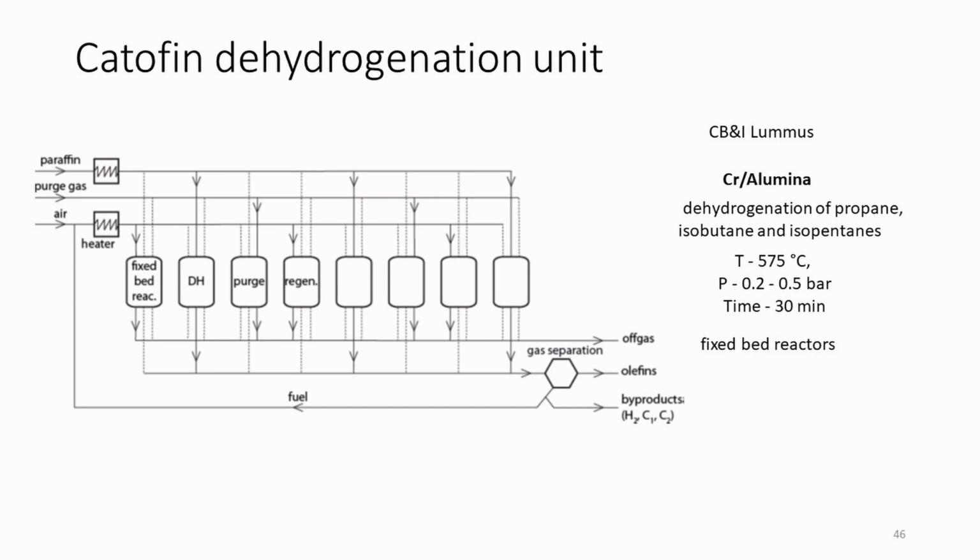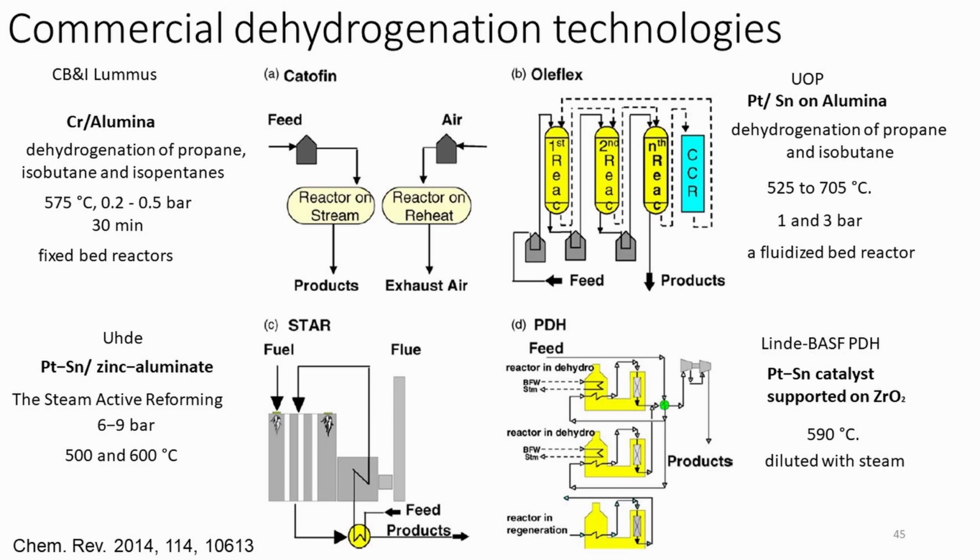The catalyst remains in use for 2–3 years and progressively loses activity with increasing time on stream, so the temperature is gradually increased to afford a constant dehydrogenation activity through the entire catalyst lifespan.